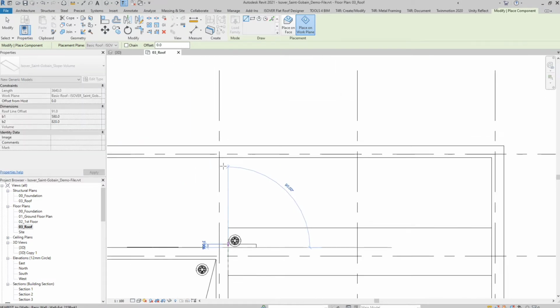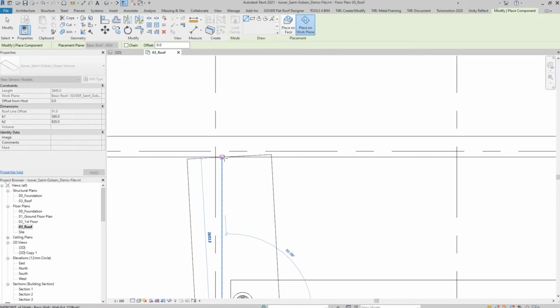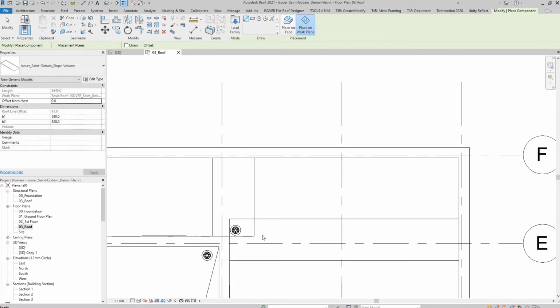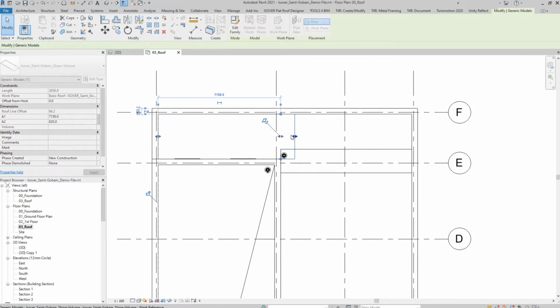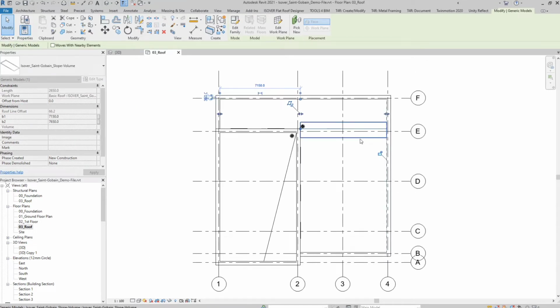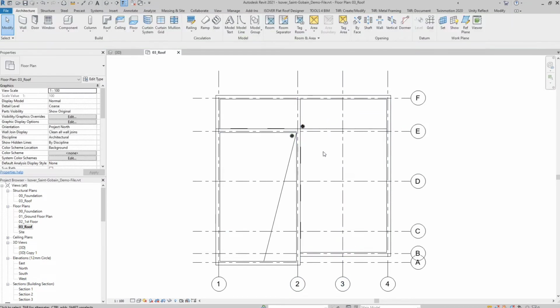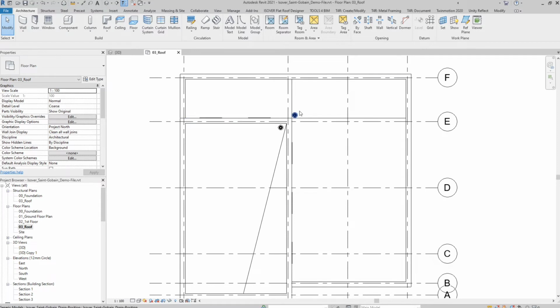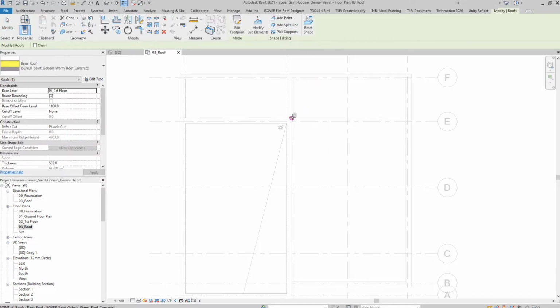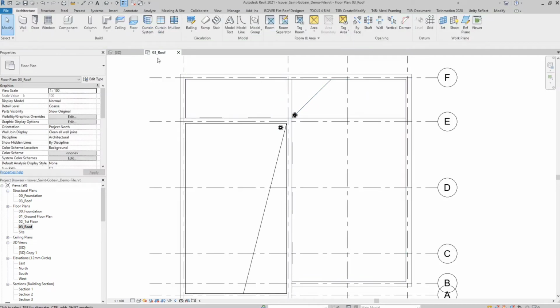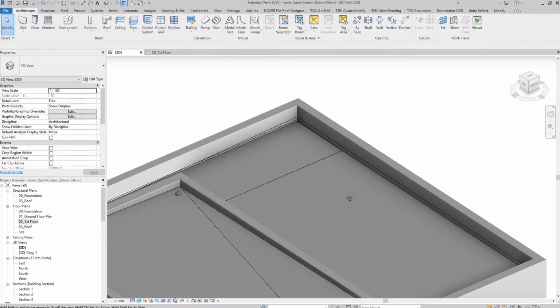Since our two roof segments are being inclined in different directions around the walls at the corner, we need to split the roof surface at the wall corner at an angular bisector, which in this case is 45 degrees. If the angle bisector is other than 45 degrees, you can draw a reference line at the correct angle, which would be used for subdivision. Since we already know our angle between the wedges, we can select the roof and use the Add Split Line to subdivide the roof surface by drawing a line in the 45-degree direction.